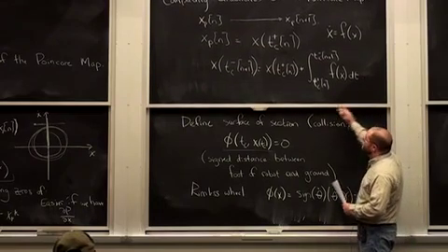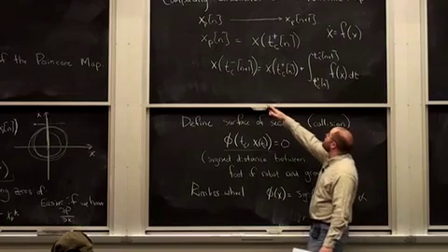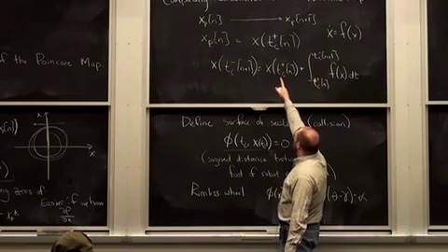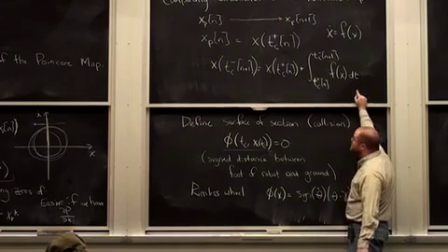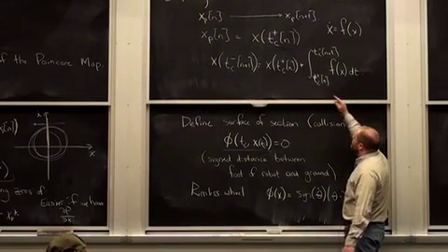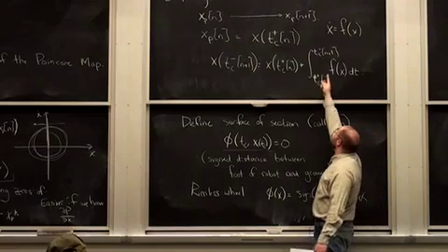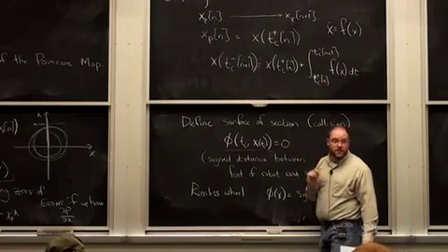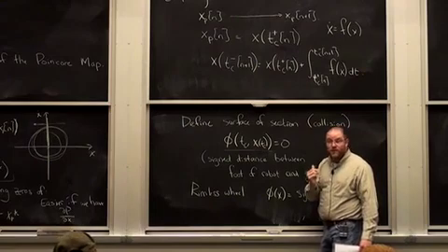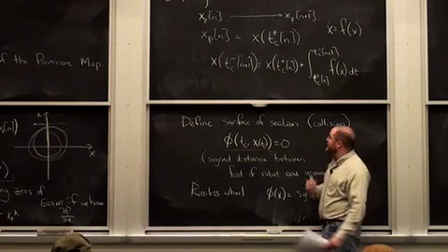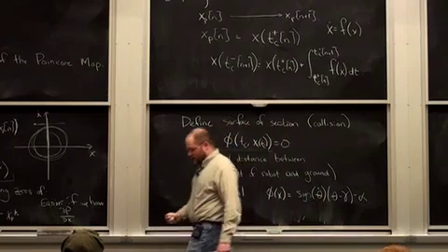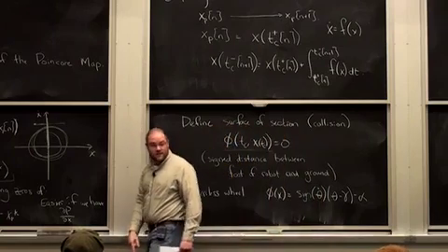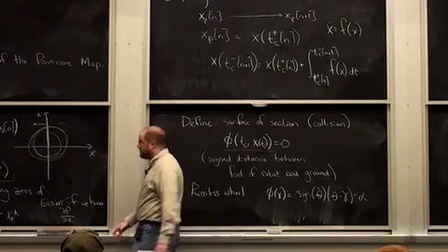Okay, so we have this x of t c minus. We've gone from just after a collision. We've integrated forward over our continuous dynamics. And so now we're at the time of the new collision, t c minus n plus 1. We're going to compute the new dynamics by having some collision function. In the rimless wheel, it was just the thing that took out some energy because of the inelastic collision with the ground.